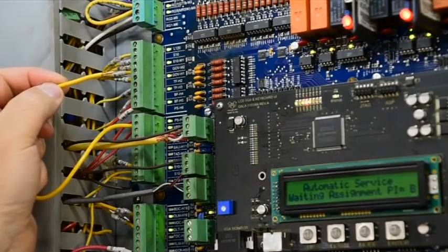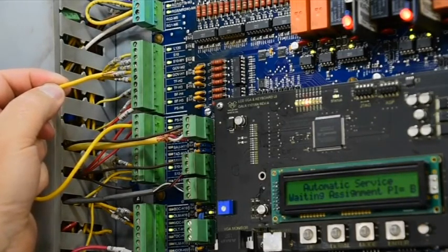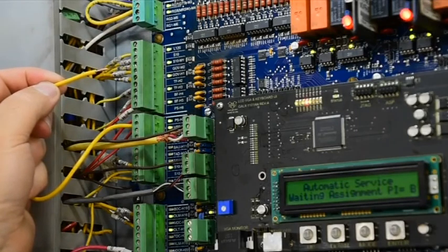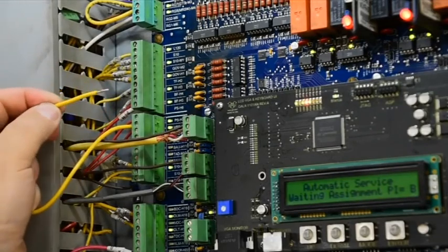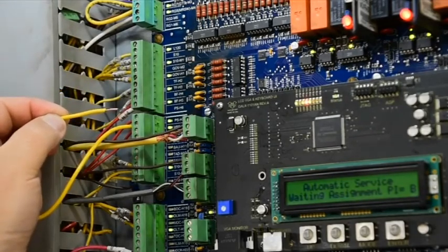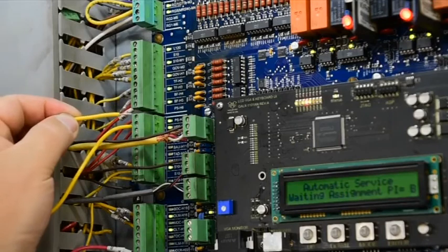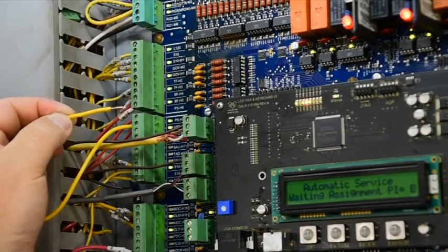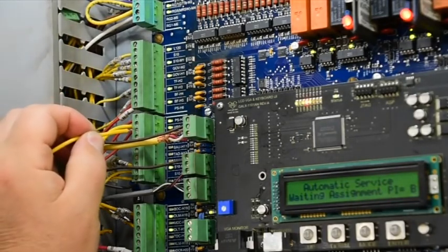Next, we are now going to verify the access input, which is the ACC. Now ACC, since it is a hoistway switch, is going to be on the left-hand side of the controller. And it is this terminal block just to the left of the CPU. It's the third terminal down. And so we are going to jump ACC hot. Now we could do that by jumping anything that's on 110. Because HSS is right next to it, we've chosen to use that terminal to make the jump. So I'm going to jump HSS to ACC.